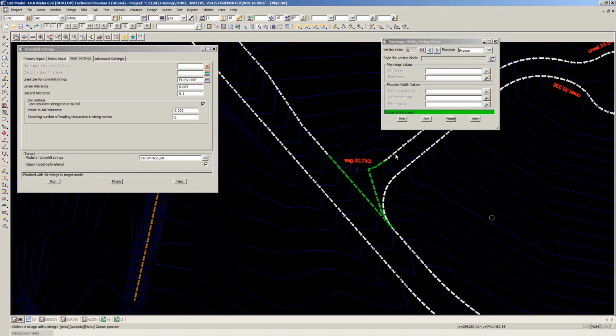And typically at an intersection like this, if I have a node here, say, I want to figure out how much of any catchment that's assigned to the node here, how much of the catchment flow comes down each of these paths. I typically like to model this sort of system where the 2 side paths here are only used to convey bypass flow, and this is where the catchment flow comes in. Really, it's up to you how you choose to model this in some cases, because nothing about what we do here affects how much actual flow ends up coming to this node. It's just how we apportion it and how we represent it on the surface before it gets to the node.